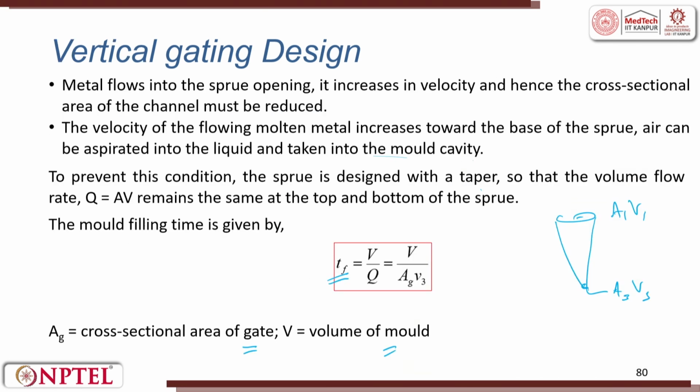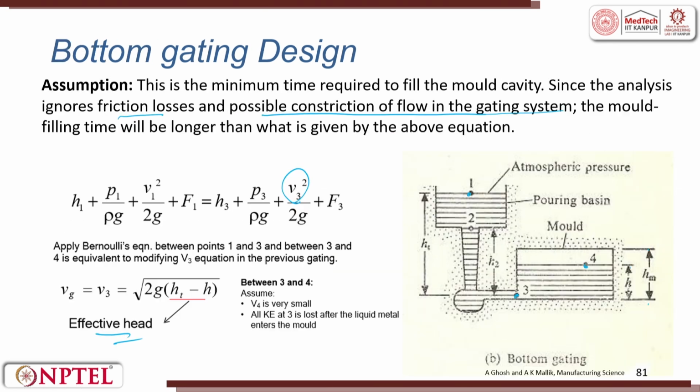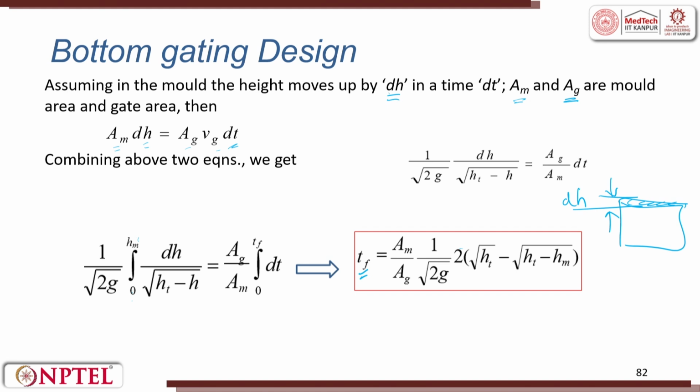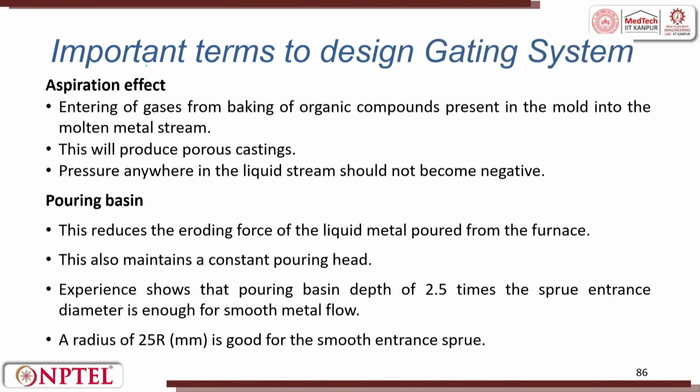In the top gating system, the mold filling time is straightforward, and in the bottom gating system, it has to be derived. So, please work it out. We will have one or two problem sessions, in which we will show it in detail, step by step. Continuing with the important terms of designing a gating system, aspiration effect. This is very important.